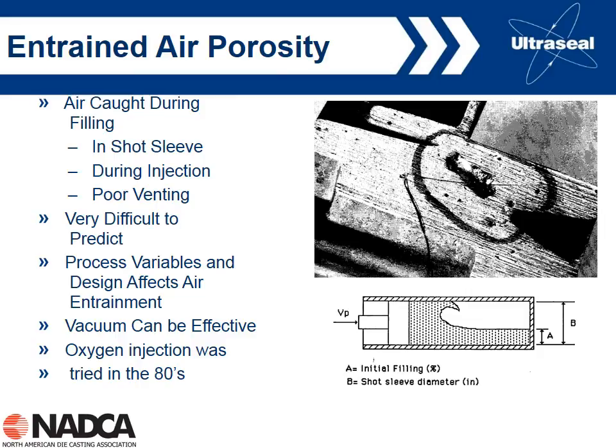But certainly, there's a relatively new process out there called high vacuum die casting, where people are making very high quality, generally automotive parts, structural safety critical parts with very, very high vacuum processes. So certainly vacuum can be effective.